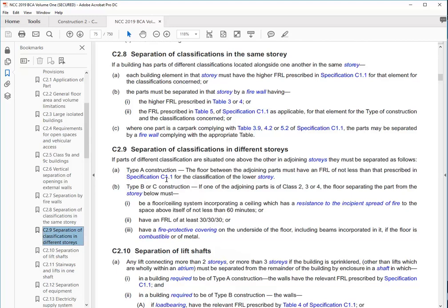The one I prefer is cassettes, which are prefabricated systems for building, which are still timber, and I think they make more sense in most cases. But CLT is a good thing too. So anyhow, have a look at that. But again, make sure you realise the walls, if they need a high fire rating, generally can't be timber. But the floors can. And that's a really interesting thing.